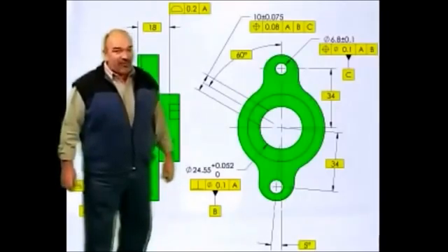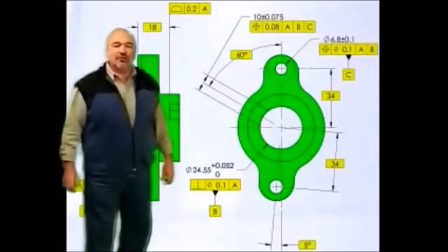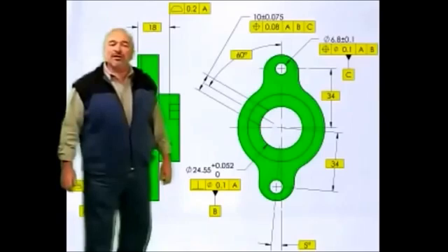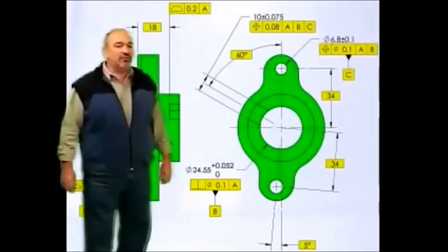If the angle of the slot needs to be controlled better than the angularity provided by the position tolerance, an angularity tolerance may be added as a refinement. As we teach in our GD&T seminars, for features of size, locate first with position and refine with orientation, but only if necessary.